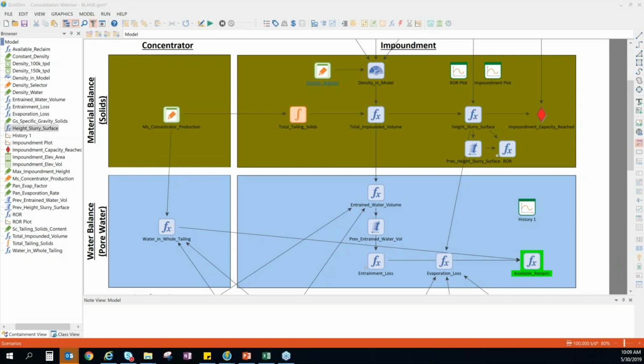And of course, as with any numerical code, with any lab test, there's limitations on how accurate we can get, because for the test and the model to be perfectly accurate, it has to perfectly represent the physical situation. And we're making some big simplifying assumptions with one-dimensional consolidation versus three-dimensional, and we're also making some big assumptions by breaking up an impoundment into columns and doing our consolidation analyses that way. So in some cases, particularly for very steep impoundments with large topographic relief, that can introduce some error, and you may need to rethink how you're developing that density curve.